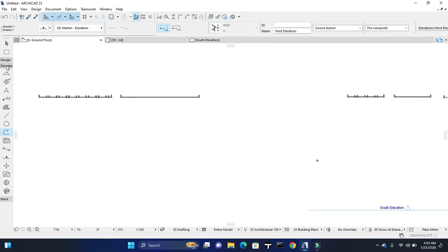Polyline is found in the second tab under the toolbox where you see document. So you go down, you see polyline tool, or you can press Ctrl+Shift+L to switch from any command to the polyline command. So now with that being in power, we have to draw a sample shape.